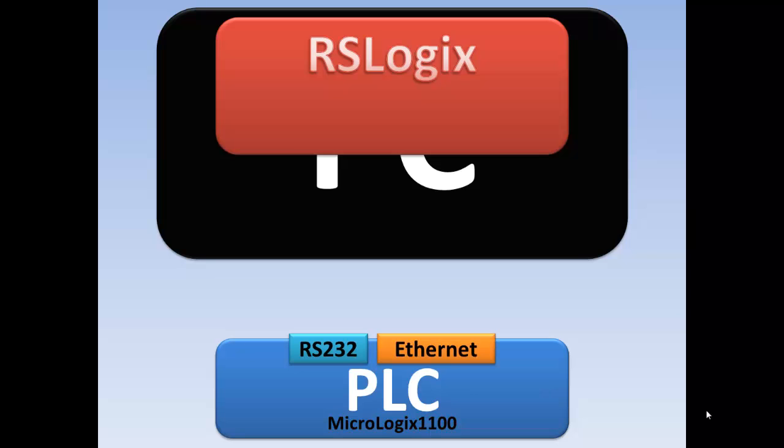The Micrologix 1100 has two ports, which gives it a major advantage. The Micrologix 1100 not only has two COM ports, RS-232, which can be configured for DF1 or DH485, but it also has an Ethernet port. And by Ethernet, I mean TCP/IP Ethernet, not EtherNet/IP or the industrial protocol, which is supported by ODVA. So this is just a standard Ethernet TCP/IP port.